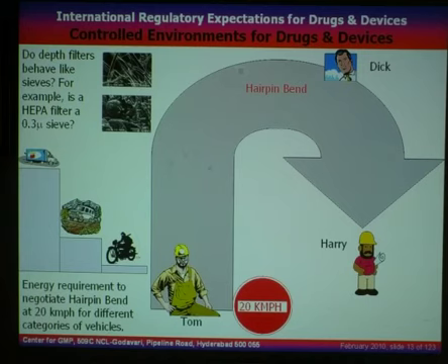Now, the cautionary signal indicates that the optimal speed for negotiating that hairpin bend is 20 kilometers per hour. If any vehicle, be it a 2-wheeler or an SUV or a truck, were to travel at 20 kilometers per hour, it could be reasonably sure of negotiating the hairpin bend safely and effectively.